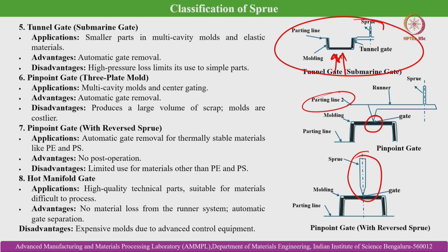This is because of the significant increase in the velocity at the entry to the mold cavity, component cavity. That is why in case of injection molding, we always use sprues which act like a diverging cylinder. But this is a special case applied for polyethylene and polystyrene, where that higher velocity does not cause much trouble. It is basically useful to make the molding at a faster rate, and also it does not create defects due to turbulence, and hence it can be applied in this case.